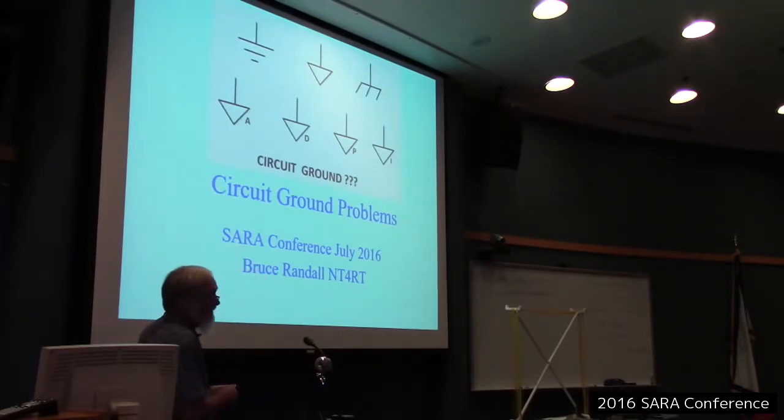Because systems will have a lot of grounds, and you've got to say, well, what is a ground? Well, the ground is a kind of a common point for a circuit. So within one circuit, all voltages will be referenced to that ground. In SPICE simulations or computer simulations, it's node 0 on the circuit. On an automobile electric system, it's the frame of the car.